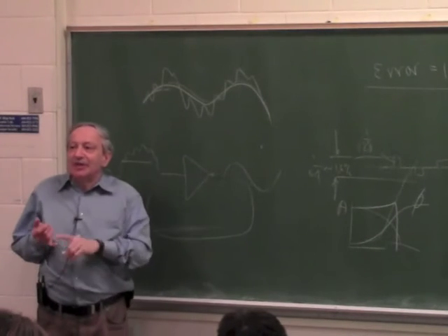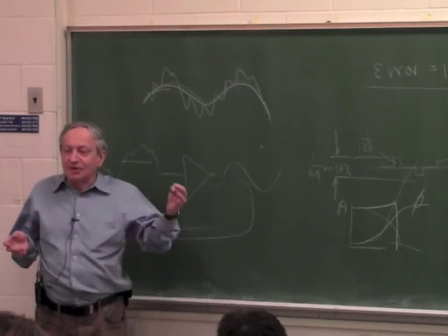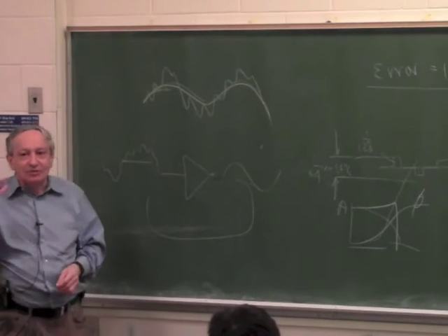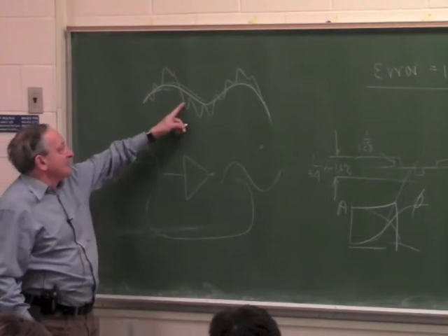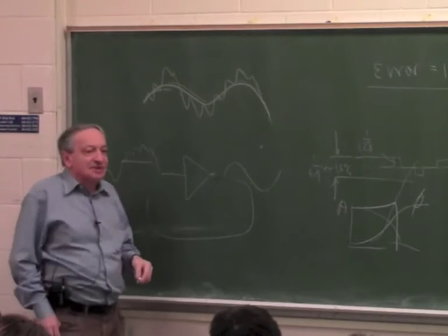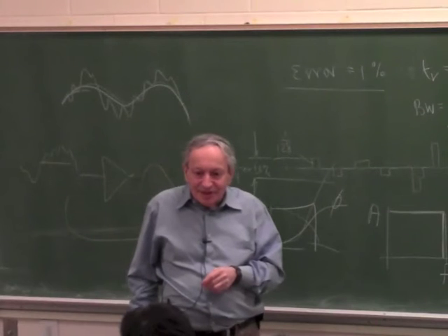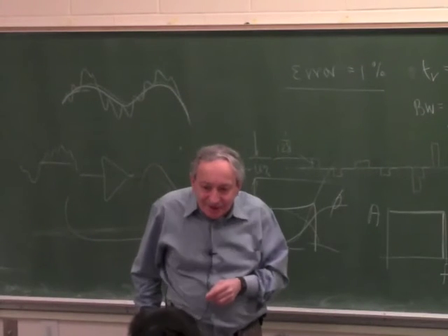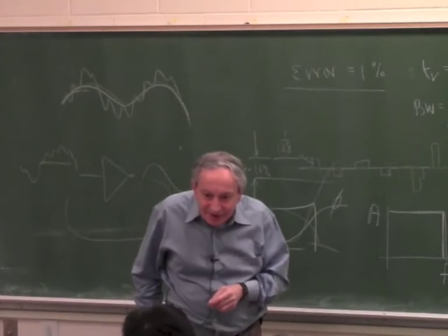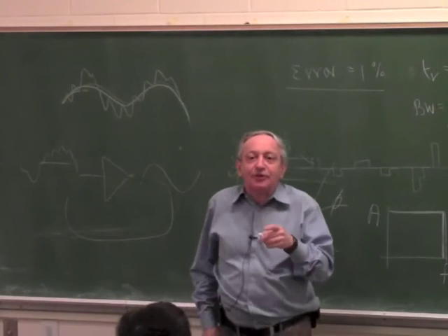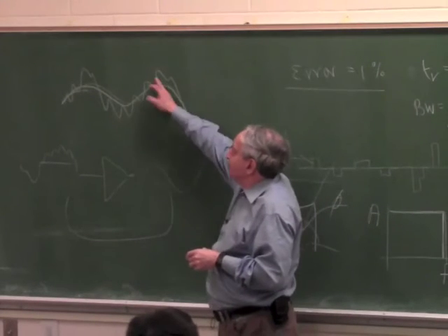So reason number one, aliasing. Okay, if it goes to a digital system. But even if it doesn't go to a digital system, there are two important reasons why you want a filter. You don't want this noise to get into the system. Yes. Because a signal with a new frequency will be generated. Okay, so the answer is a new frequency can be generated from these two frequencies.